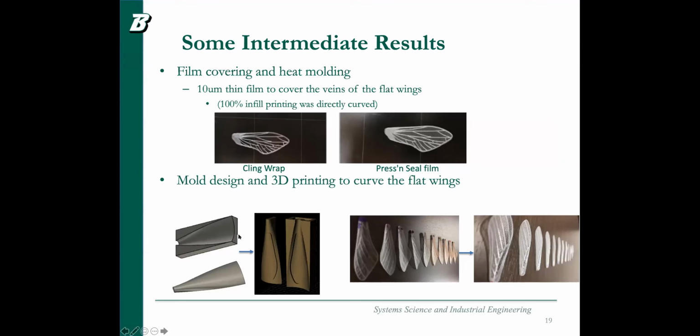different designs of the mold. The first version of the mold looked like this, without any structure to hold the wing, but the final version has a structure. For the first version, the initial ones, we could put the wings anywhere. So they may slip when we do the manual heat molding. It can change location anywhere. That means the curvature will not be even, and the wings may slip around.